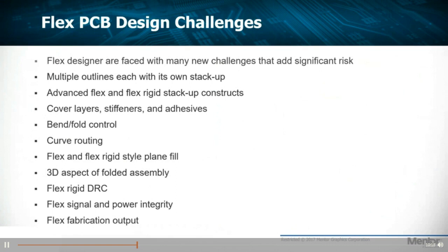Bend and folding control can be accomplished very easily within the PADS Professional space as well. We have easy ways to fill plane shapes with a hatch design or hatch plane in order to fulfill rigid flex requirements. And then also built into the tool is full DRC specific to rigid and flex areas of the board. Okay. So that can be very important to make sure that you're still adhering to the design rules that you've set up and you're going to output a high quality product.